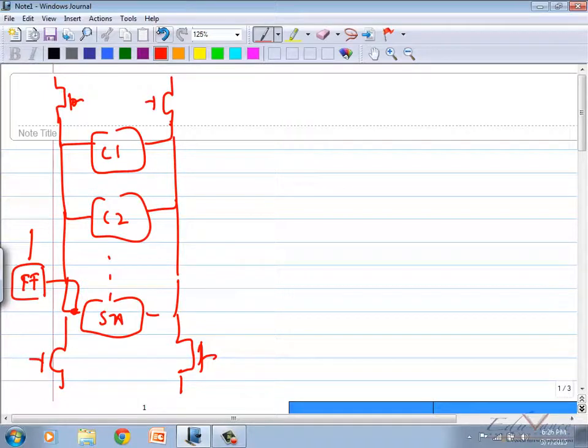Because somewhere the controller has to give the signals. You can't put it on your microcontroller's head, telling it to give precharge, give this, give that; it will say I'll just make everything myself. So inside the SRAM there is a clock and there is a controller. Basically, what does the controller do? It will give precharge, then your sense enable, write enable, data enable, and then when to enable the flip flop, so that the data also appears on the flip flop's output. All of this is handled by the controller.